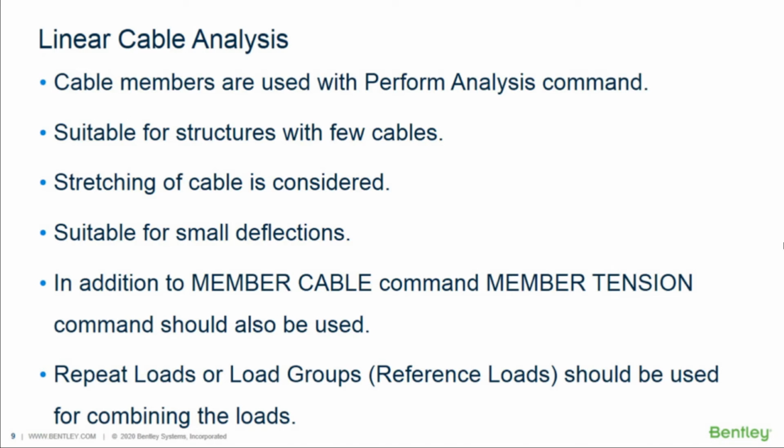In addition to the member cable command, you also have to use the member tension command. This is to avoid the cable members taking compression. Repeat loads or load groups should be used for combining the loads. I already explained the purpose of load groups in my previous tech talk in April.